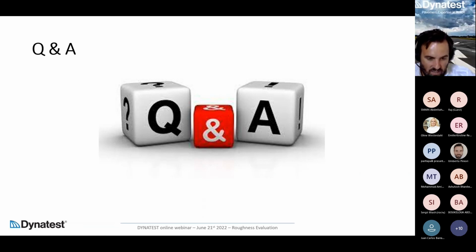Praveen asks, you need calibration for the profilometer, right? Yes, in our case, calibration is different for Mark III and Mark IV RSP. For the Mark IV, that is the portable one, the calibration is a self-calibration, so you need just to verify the calibration. Mark III has a calibration procedure that can be provided by the operator, so it can be done regularly or before any collection, but the user can perform it himself.